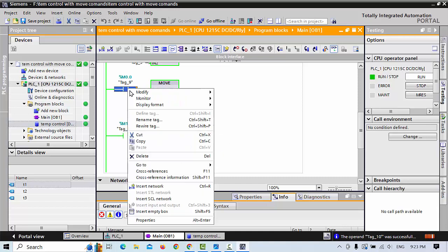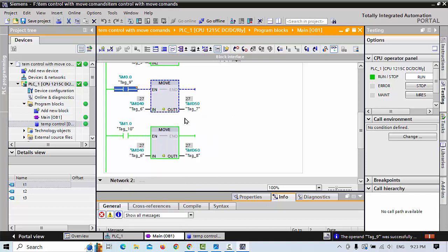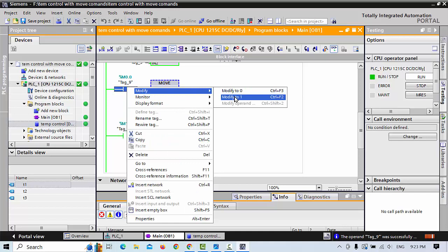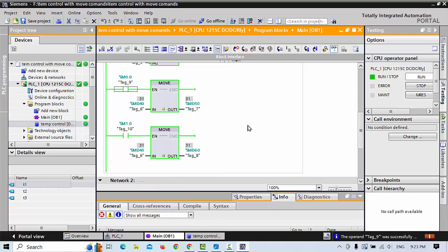And when you stop this execution, your temperature keeps increasing, but this will not move. See now 28, 29, 30, but this is still at 27. This will not move, and your compare command will not energize your next command. As I turn this one on, it will move.